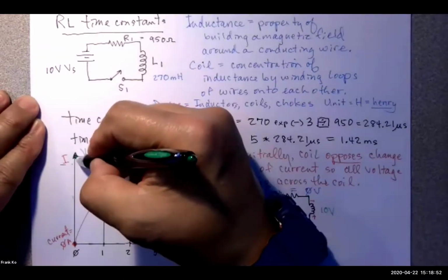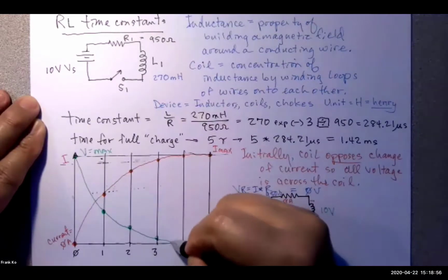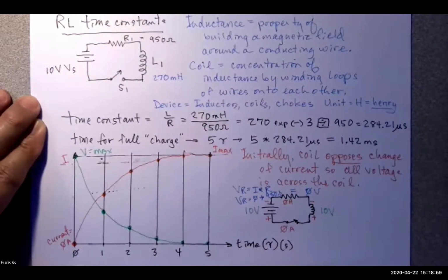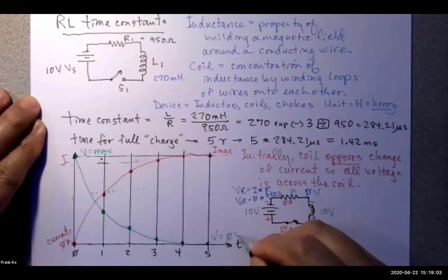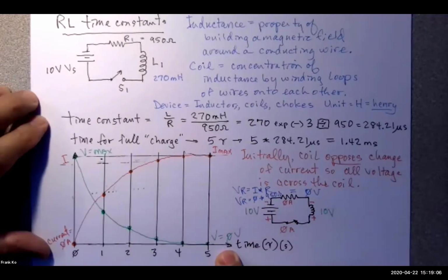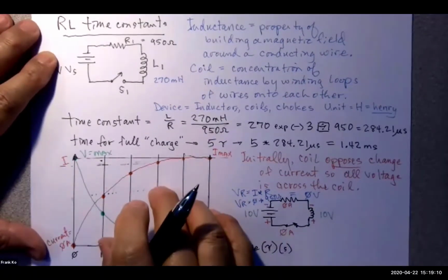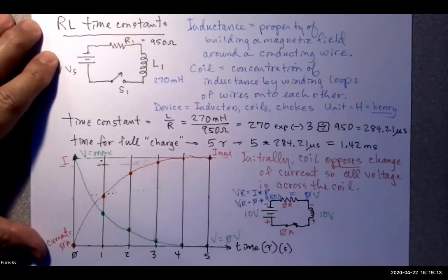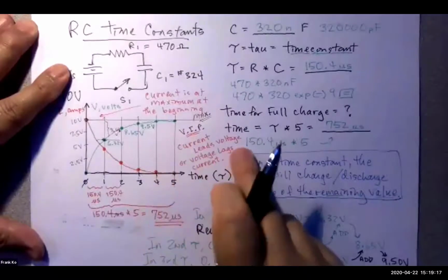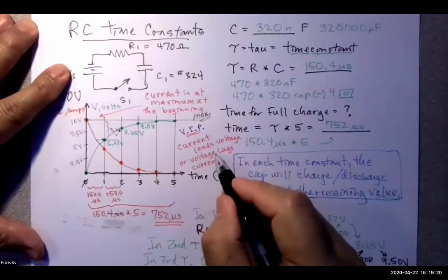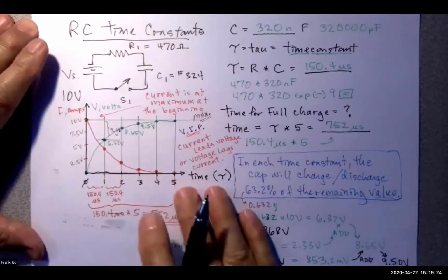I will go to connect the dots. When I go to connect the dots, I end up with this, and now V is equal to 0 volts at the end. Can you make a concluding statement similar to what we had before? We made a concluding statement before, very important point. Current leads voltage or voltage lags current based on a capacitor circuit.